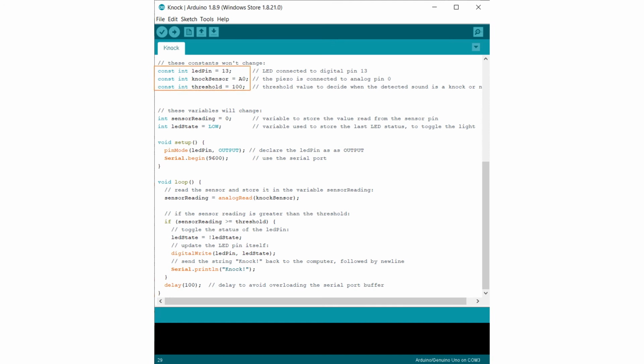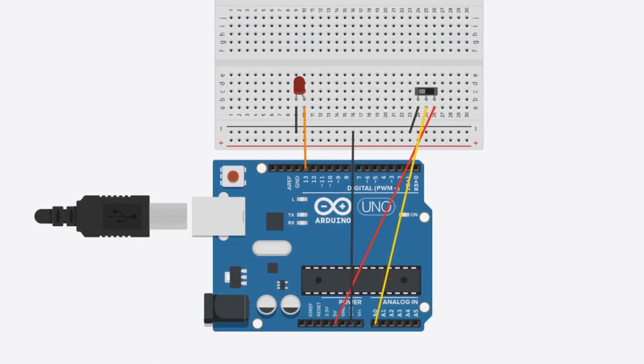The piezo input is on analog pin 0, and the LED output is on pin 13. Notice the threshold given in the orange box. If desired, the threshold can be moved to 600 or higher for a greater signal required to set off the light. Like the piezo, the LED can be replaced with another actuator such as a buzzer or flexinol to provide a different output. Here's the layout for the thresholds example.